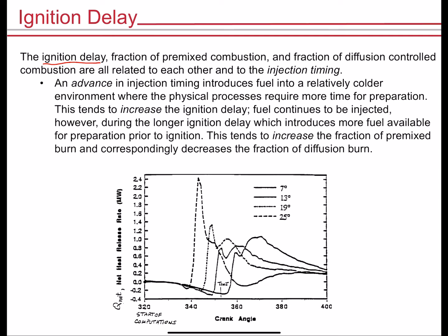And by the way, the other thing that we really haven't talked about here is the combustion duration. The combustion duration is just that. It's the time from start of combustion to end of combustion. Right? So let me just define these things. We already know what ignition delay is, right? That's the time between start of injection and start of combustion.